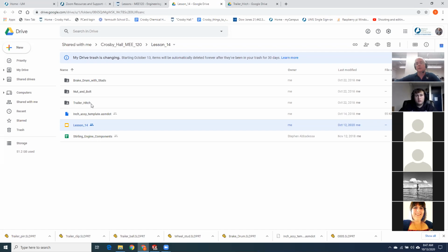You mean like save the individual parts that I downloaded from the lesson? Yeah, what I see a lot year to year is people will do the drawing, everything's great, looks fine. They'll close the drawing and the models, and then they'll say, oh, I don't like the name of this, I want to change it. Maybe put your name on it, put your initials on it, and that screws up the link between the drawing and the model.